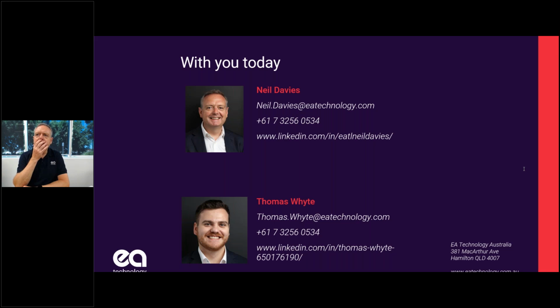Okay, the limitations. So what are the limitations on this technology, if any? Is it more superior to offline PD test? They all play a part. The good thing with online type testing is you're testing things as they are in service. Everything is running as it is. It's three-phase testing, whereas offline testing is often single-phase testing.